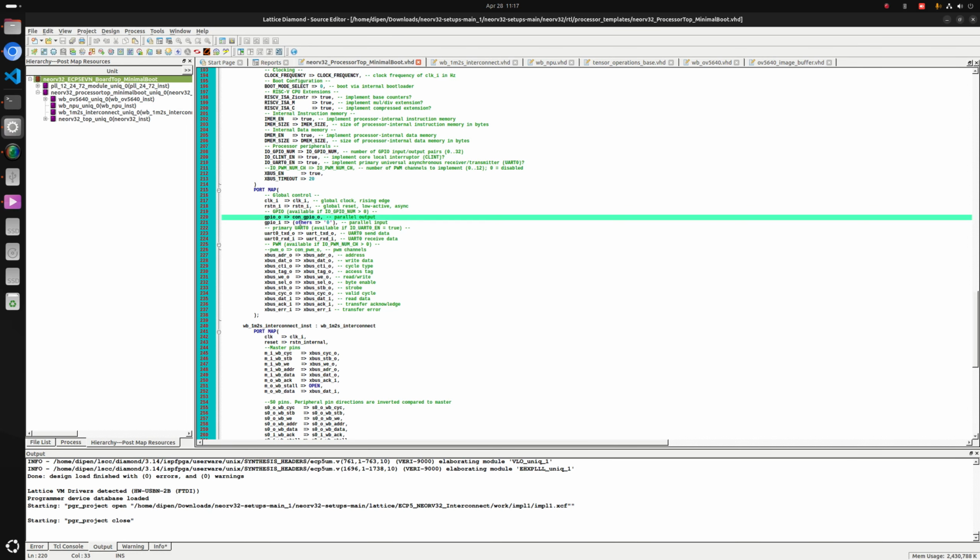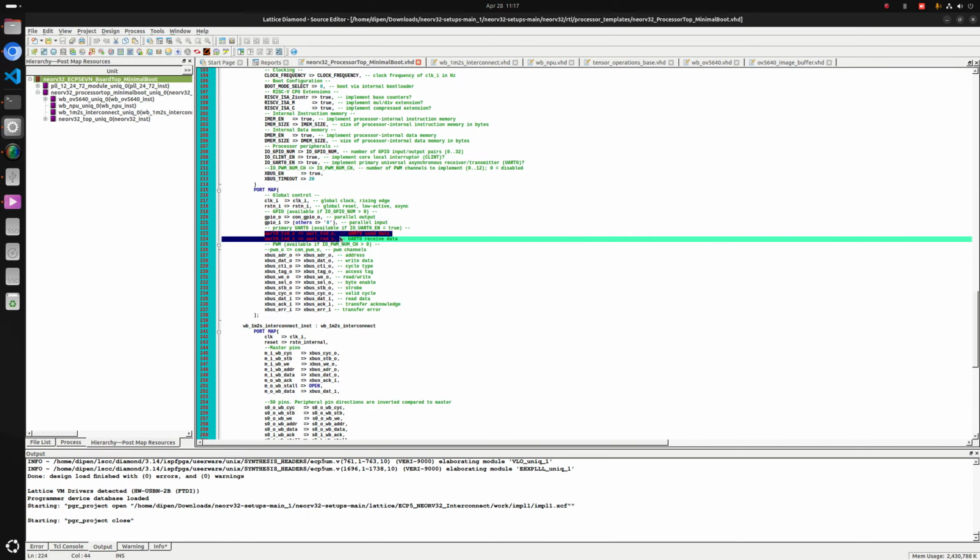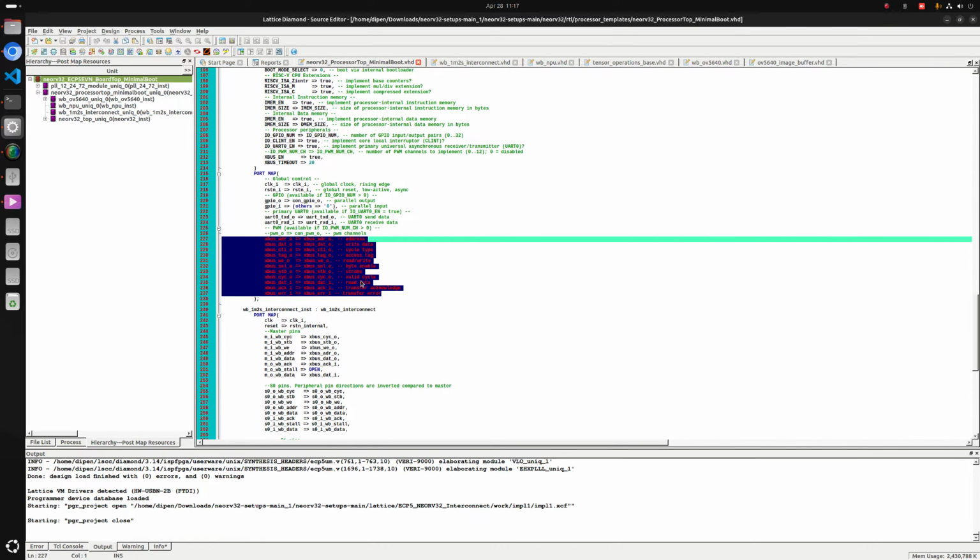The output pins and input pins are tied to 0. We are not giving the NEORV32 any specific physical input. We pass the UART interface pins from the ECP5 physical pins, and these are the XBus pins used internally.